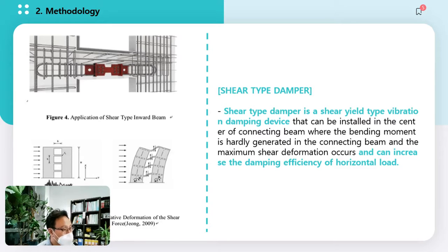Figure 4 shows the installation locations of the shear coupling beam and the damper. The energy dissipation device can be applied to the shear wall to minimize damage to the structure by utilizing the deformation and cross-section force of the shear wall. Figure 5 is a diagram that distributes the shear force of the coupling beam on the behavior of the building during an earthquake.